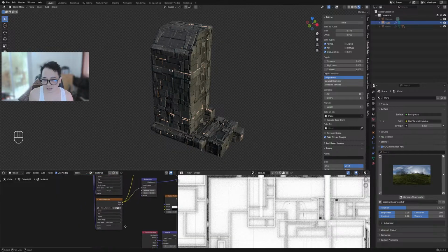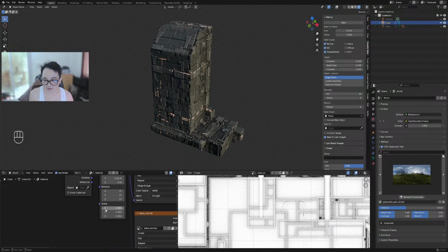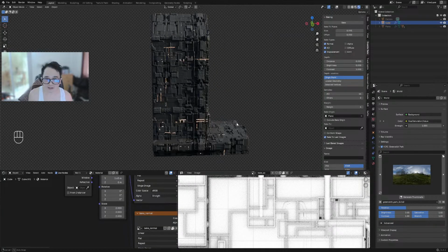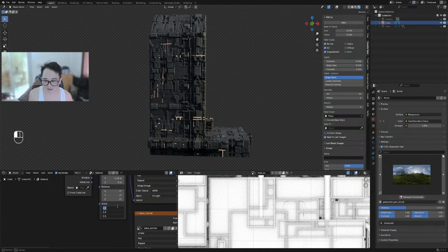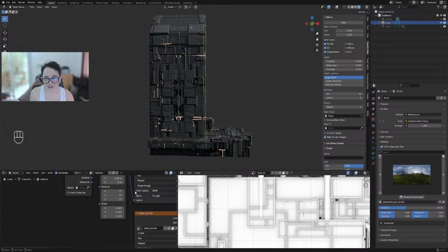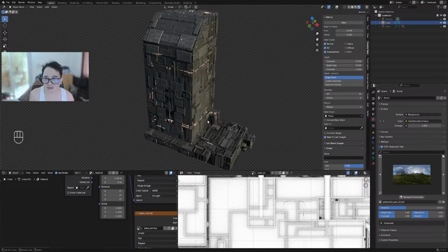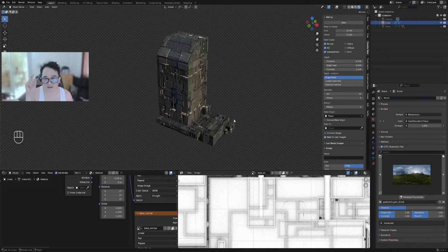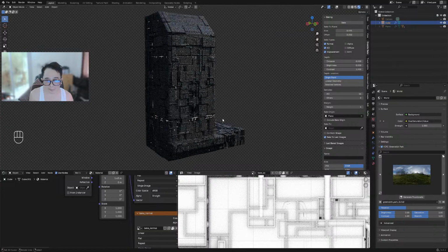And the good thing about this is that you can just change the position of the details to create another look. You can select an object, then duplicate that material using this paper icon here, the new material. Then you can change and modify its settings without affecting the other ones. So if you want a unique look for that particular mesh, you duplicate the material. Be sure to rename it so you don't get confused in the long run.